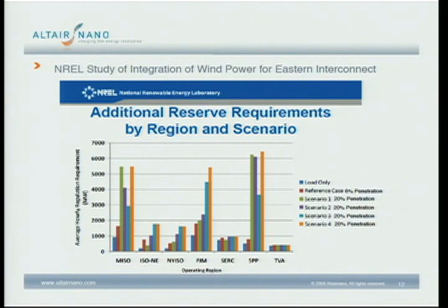And that's, roughly, in California, about $20 a megawatt hour. In New York ISO, it's about $50 a megawatt hour. And as you go outside of some of these areas that use natural gas, the price even goes higher. The cost of regulation was going higher and higher along with the cost of natural gas, where in most of the control areas, PJM, MISO, and in New York, it was still high. It was approaching $40 to $45 to $50 a megawatt hour. That provided extremely good investment opportunities for storage to do frequency regulation.